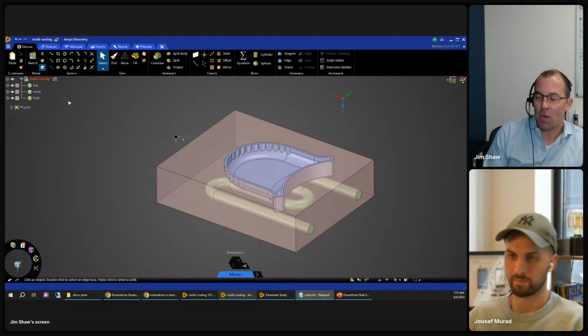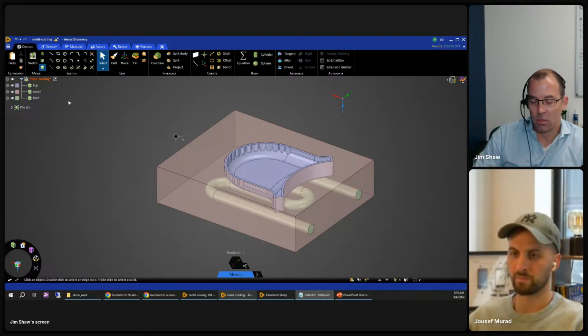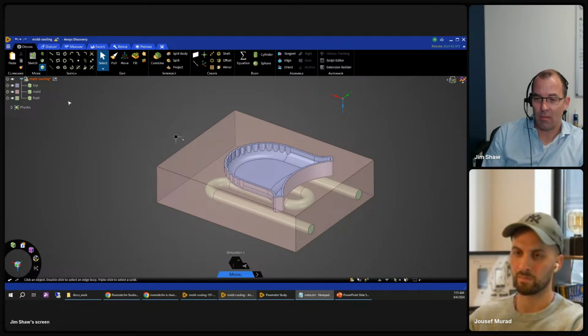A lot of times you're starting with a customer's or a partner's CAD data, and 9 times out of 10, that's going to come in as a STEP file. STEP and IGES are the two internationally known common denominator geometry files. The reality is you do lose a tenth or a hundredth of a thousandth, depending on the CAD import, and that can add up sometimes. So it's kind of a pain.